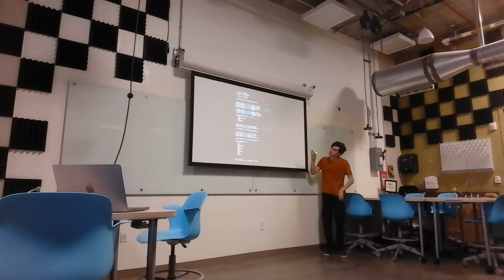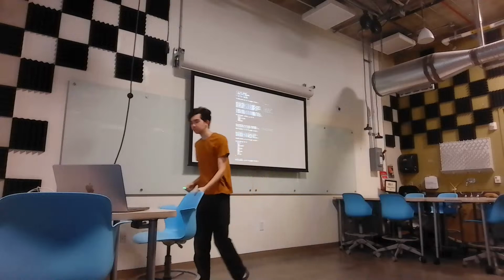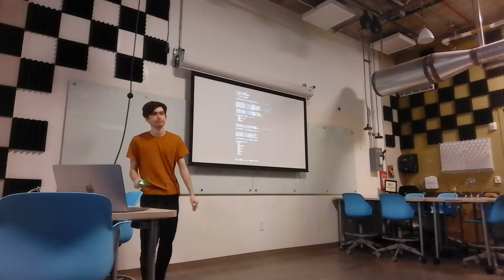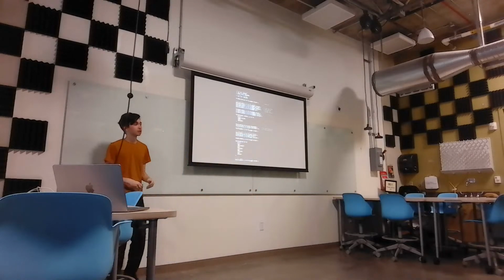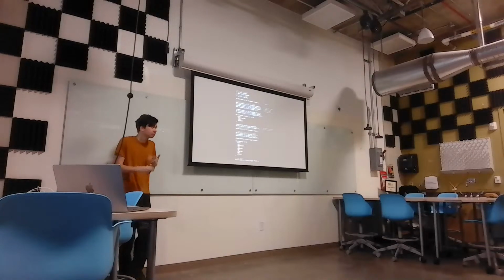So this was the first thing I ever did with embedded Rust. That's when we put Rust on an embedded system microcontroller. I knew that I could instruct the microcontroller to output what's called complementary PWM. So we have multiple PWM signals where one is always the opposite of the other. That's called two channels. You can configure the PWM peripheral to just do that. It has the ability to do that.